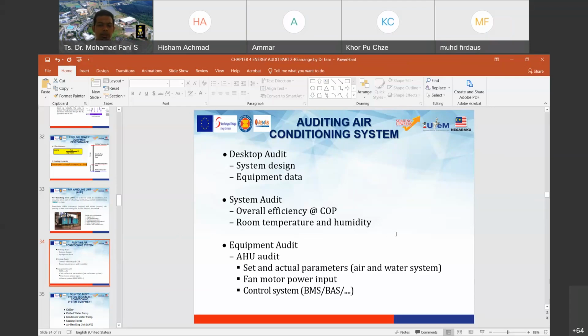It will become moldy. If you look at the library, you can see it in the shielding if the humidity is not right, and then we need to do something, setting the chiller temperature and also the fresh air percentage to get the proper temperature.